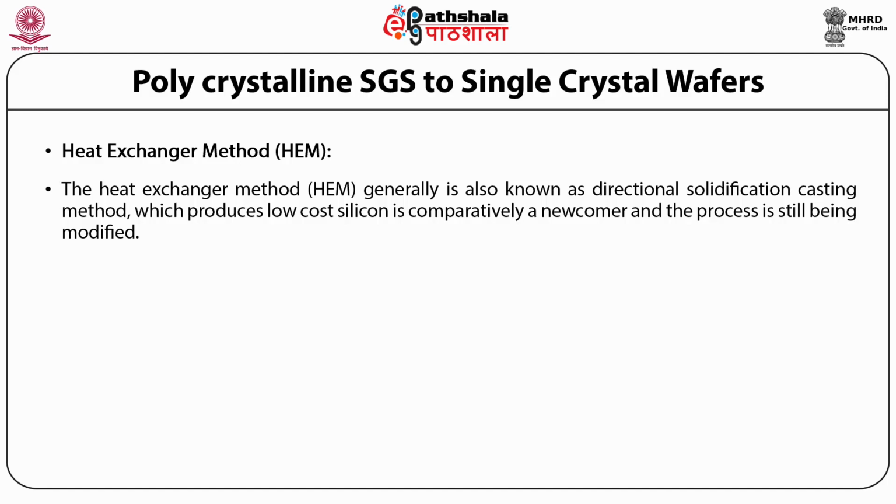In this process, a block of silicon with side 30 to 35 centimeters can be produced, which is a single crystal except for around the edges. Finally, the square wafers can be sliced from this square rod using normal methods. This method is able to produce large amount of silicon single crystal.